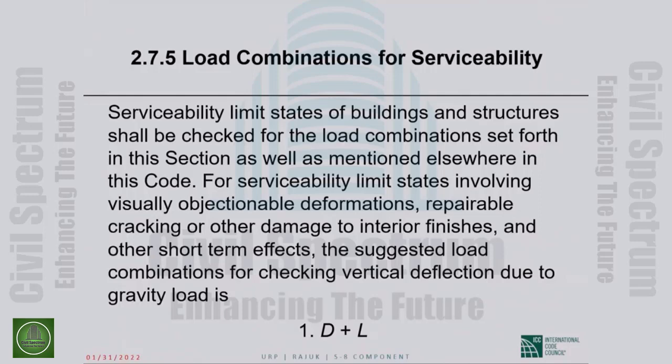Okay, that brings me to load combinations for serviceability that I mentioned is in the code. So now let us get into that. Okay, so serviceability limit states like acceptable deflections, cracking, and so forth. Serviceability limit states of buildings and structures shall be checked for the load combination set forth in this section, as well as mentioned elsewhere in the code.